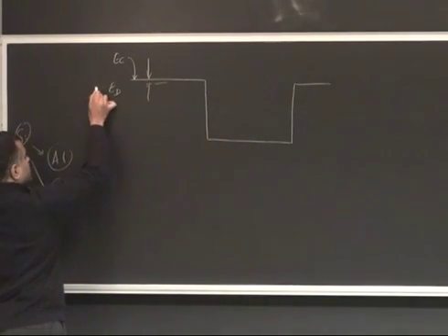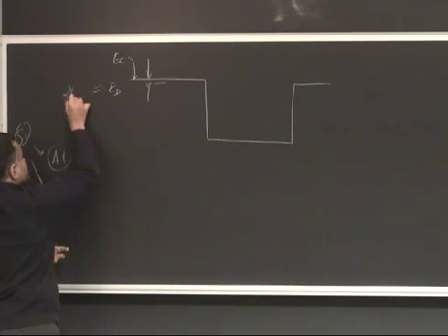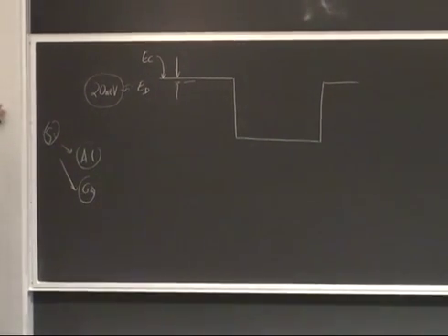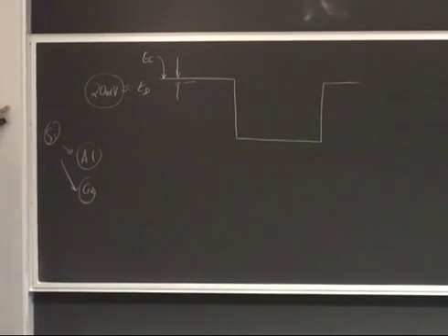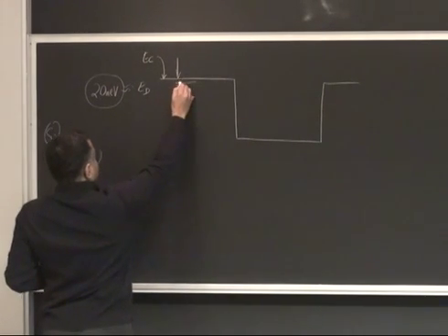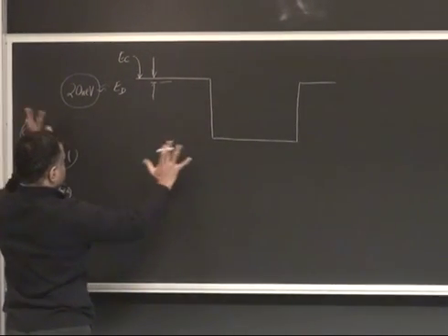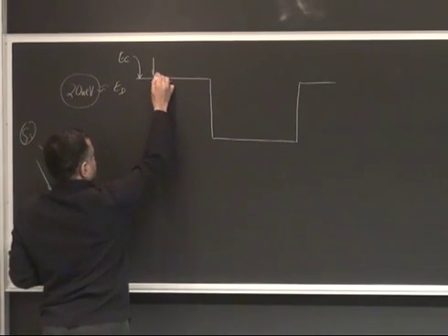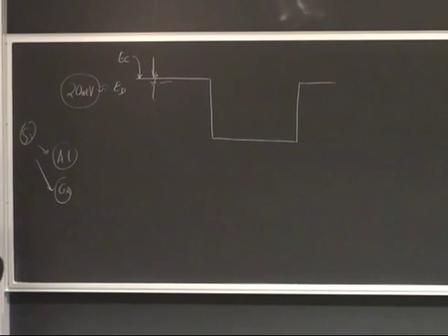And typically the donor ionization energies would be just as an order of magnitude, you would like it to be smaller or of the order of room temperature kT. kT is 26 meV. Why? Because then that electron that was tied to the silicon atom, because of the atomic vibrations at room temperature, gets enough kinetic energy that it's kicked out into the conduction band. Thermally ionized. It's ionized. Okay?